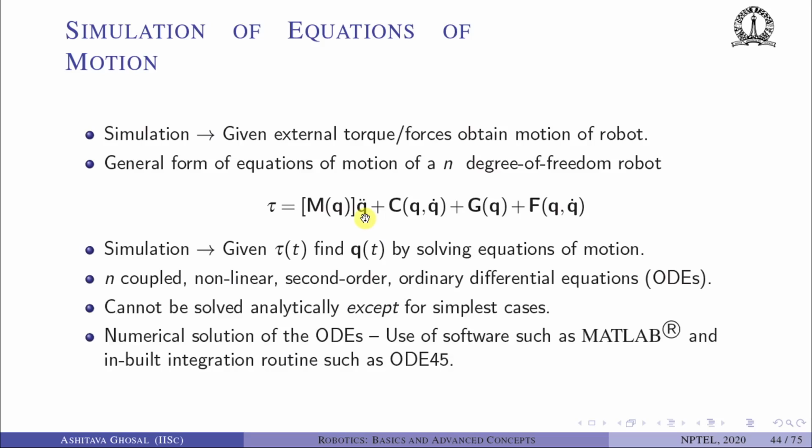We cannot solve these things analytically, except probably in some very trivial simple case. Remember, this is nonlinear. It has sine theta, cos theta, theta 1 dot square, theta 2 dot square, all kinds of nonlinearities. So we need to resort to numerical solution. We go to MATLAB.